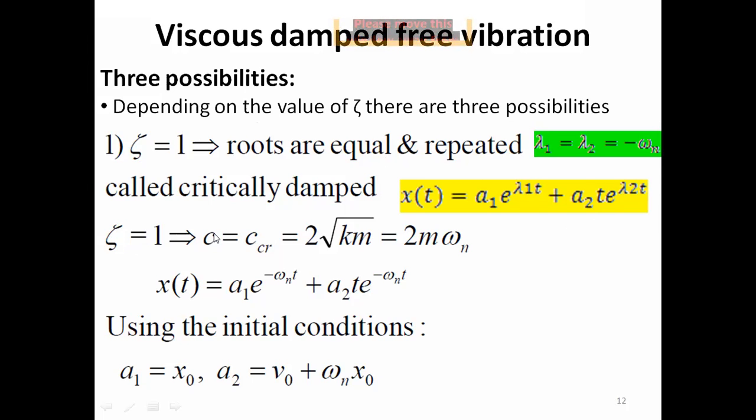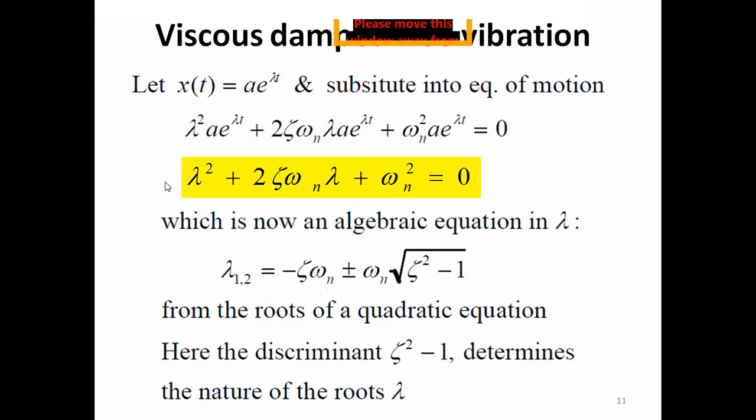So if the actual damping is equal to the critical damping, then in that case the damping ratio would be 1. And when the damping ratio is 1, if you look at this equation, the square of 1 is 1, so 1 minus 1 is 0. So this quantity would become 0.